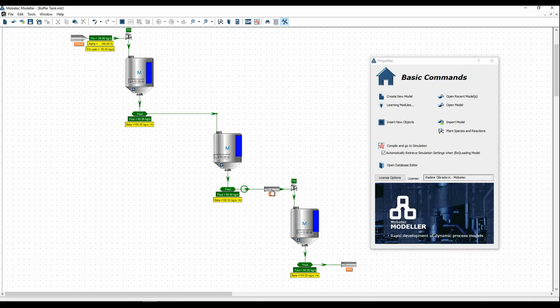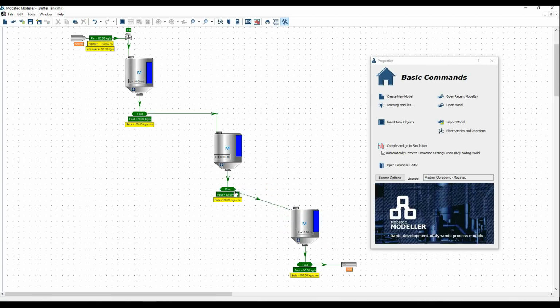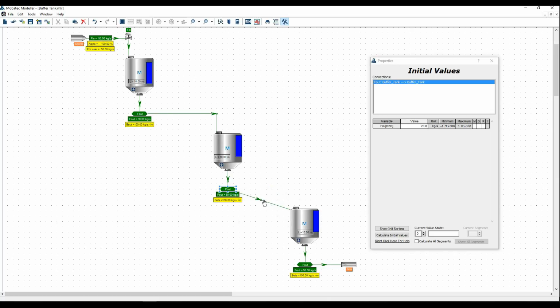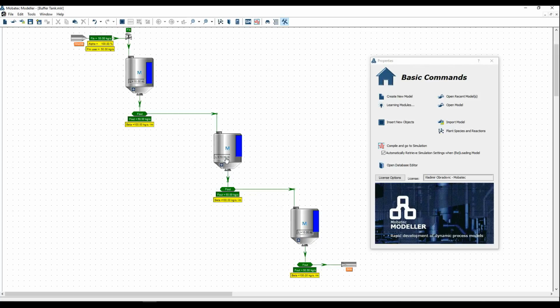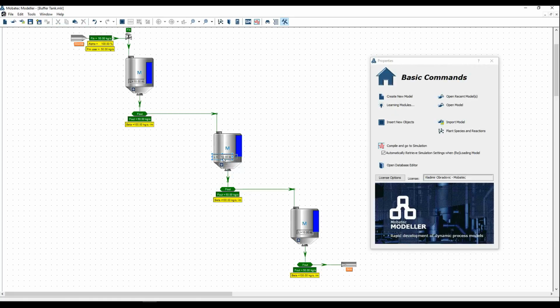Do the same for the second tank. Connect the outlet connection to the tank. Also add 3 bending points to make it look nice. Now you can adjust a bit the position of your displays, as they may move a bit once you copy your tanks.